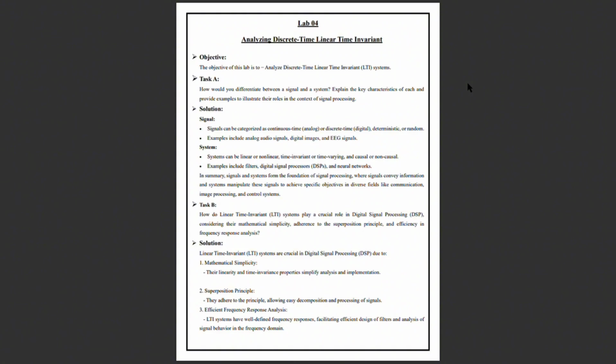In task B, how do linear time invariant systems play a crucial role in digital signal processing? Considering their mathematical simplicity, adherence to the superposition principle, and efficiency in frequency response analysis. Solution. Linear time invariant systems are crucial in digital signal processing due to mathematical simplicity. Their linearity and time invariance properties simplify analysis and implementation. Point 2. Superposition principle. They adhere to the principle, allowing easy decomposition and processing of signals.